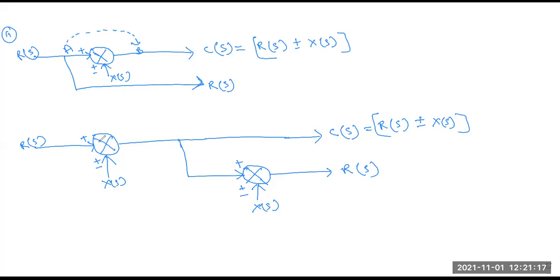This is the previous one. It is the same as this one, and this summing point changes to another summing point, and the previous output is connected from this one to this one also, and another part, the complete controller output position, we have to receive from here. Okay, so this point changes from this takeoff point to another point. This type of rule we have to apply in our different types of problems. Okay, is it clear to all of you?